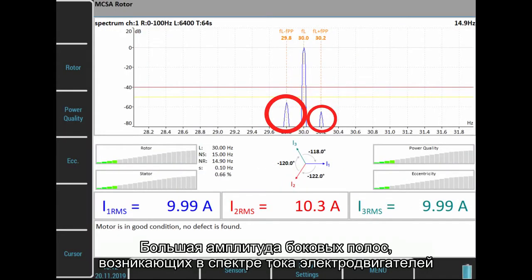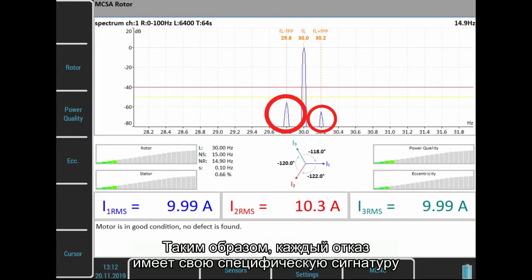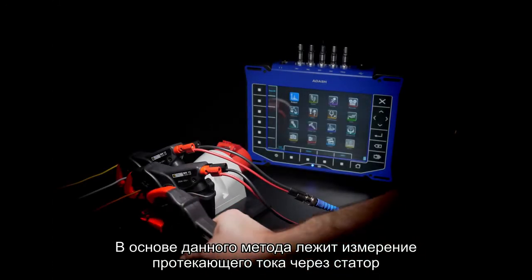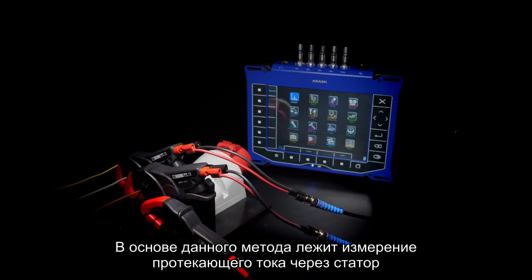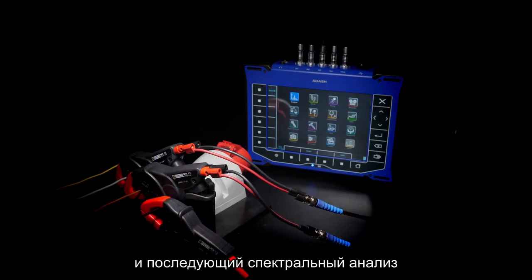Excessive sidebands are created in electric motors which distort the frequency spectrum. Each fault then has its specific signature. Individual defects can be distinguished from each other according to the amplitude bands and the frequency or other signatures. The basis of this method is to measure the course of the stator current of one or more phases in the time domain and its subsequent spectral analysis.